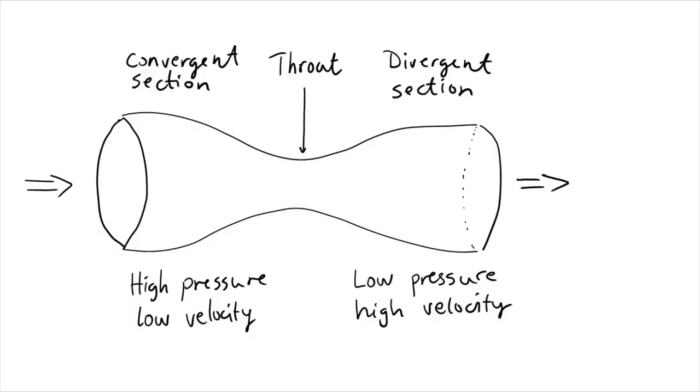In this video we will create a two-dimensional axisymmetric De Laval nozzle, and later on we will also mesh it before we import it to ANSYS Fluent. The De Laval nozzle is composed of two different sections. We have one converging section and one diverging section.